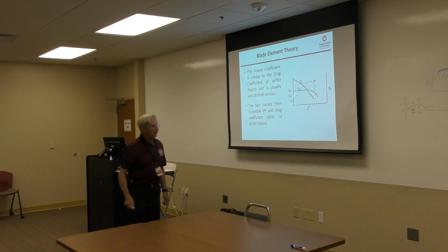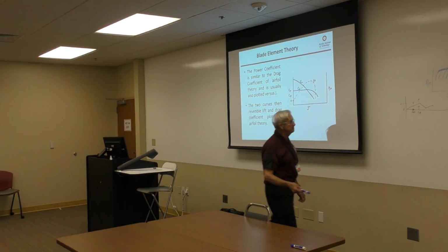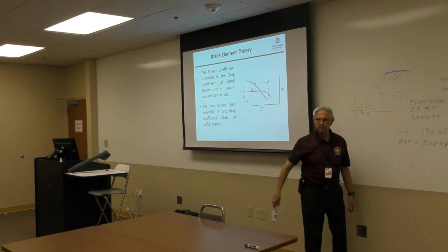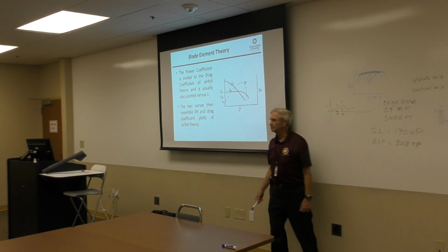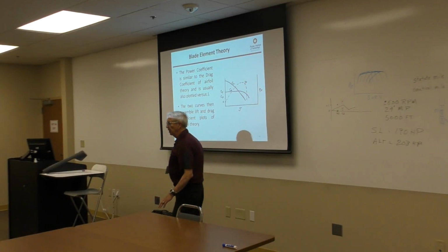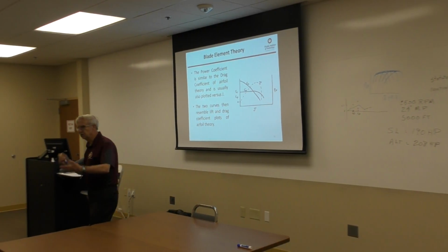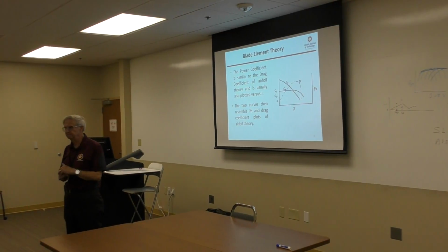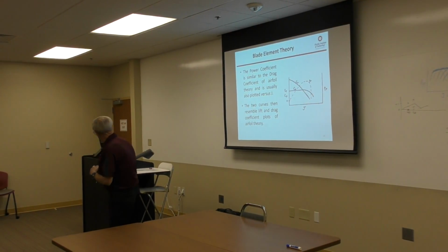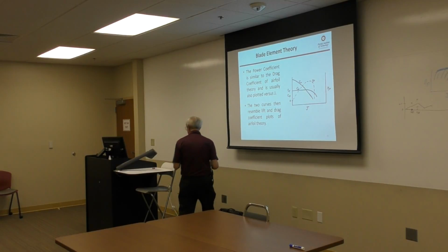And so that's the purpose of a constant speed propeller, that you're operating up here on the tops of all these curves throughout the speed range. It's changing blade angle to maintain that position. Okay, does that make sense?